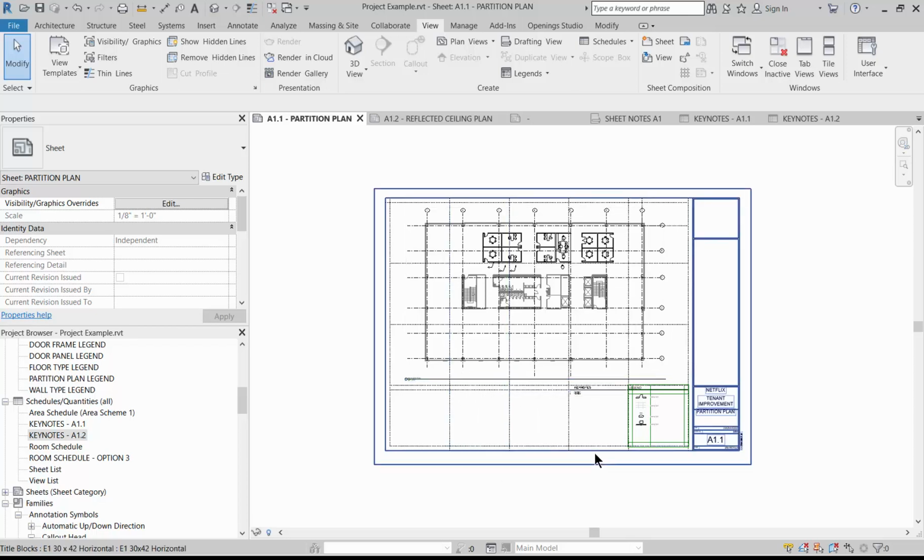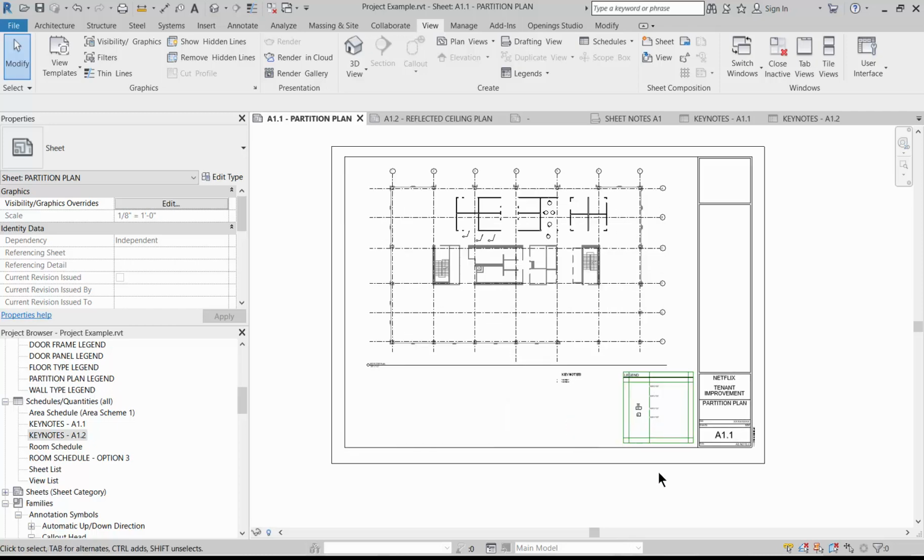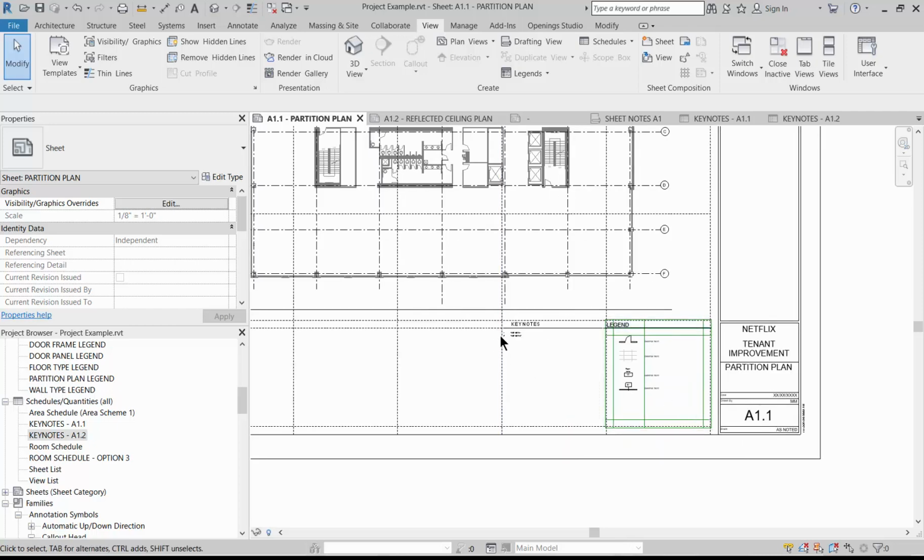So you should proceed with your mock set and create the sheets. Each sheet should have its views, and even if the views are not completely drawn, set up your elevation, set up your enlarged floor plans using the callout command, and create a legend for each sheet and create a title keynote block. Now what you will have on certain sheets in addition is the sheet notes.